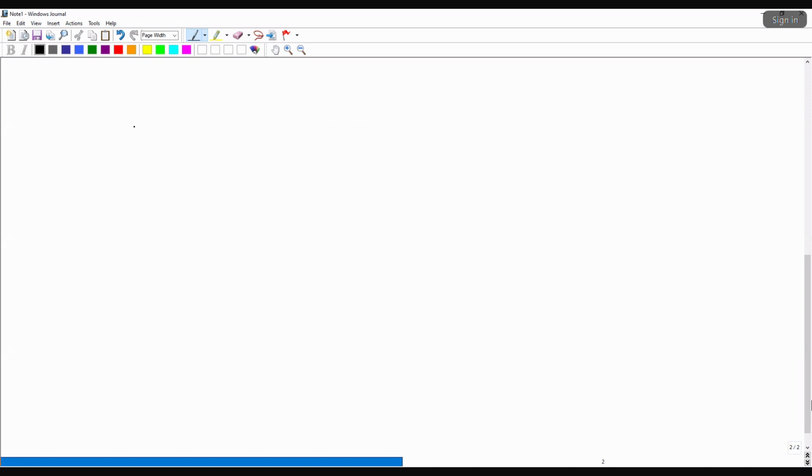So in an oven, basically you have a heater. This heater basically heats the environment inside and controls the temperature. Let's say you have set some temperature, 70 degrees, right? This is the set temperature, and you have a thermocouple inside, and this thermocouple is basically measuring the temperature.